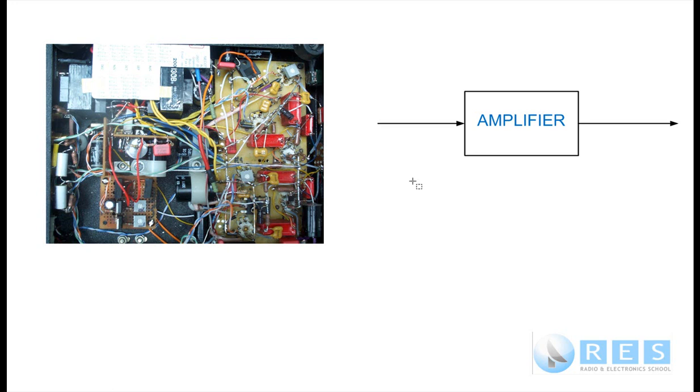Let's suppose the amplifier is designed to operate on 7 megahertz, and let's suppose that in the amplifier, unbeknown to the builder, there are resonant circuits on 7.1 megahertz. And let's also suppose there is enough positive feedback, and this amplifier, which is designed only to amplify 7 megahertz, begins to transmit a signal on 7.1 megahertz.